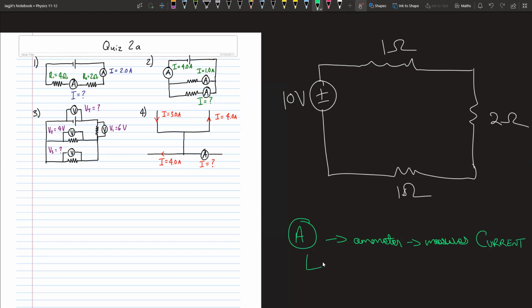And you should know that you need to place the ammeter in series. It needs to be placed in series if you want to measure the current. Means what you would do is, you will take the ammeter, this will be one side of it, this will be second side of it, and this will be the ammeter, and you will just put this in series. So we'll take your wire and you will hook it up on one side right here. You hook up the other side of the circuit to this ammeter.